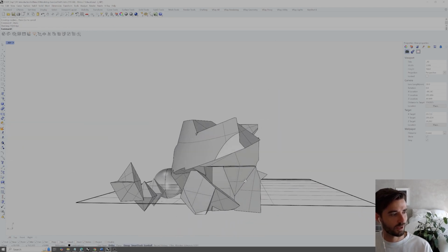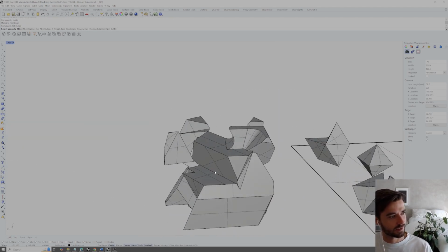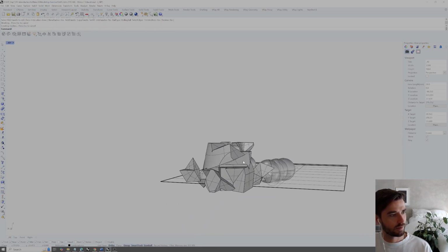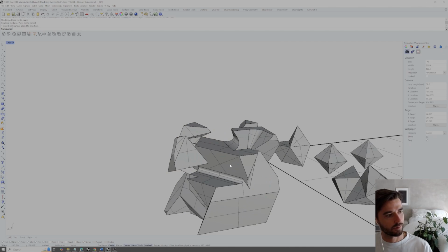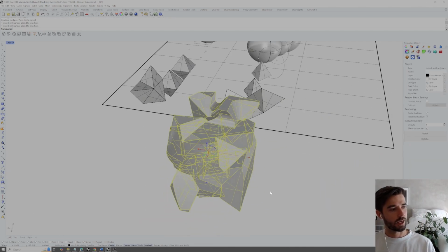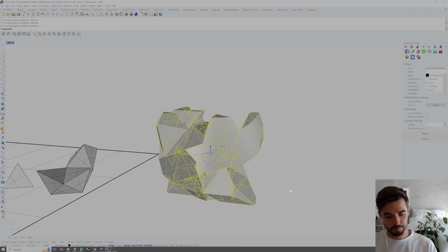It's not wanting to. Okay, then I will go ahead and skip that. Okay, there you go. It's still a closed solid poly surface. Okay, so now what I'm going to go ahead and do is select that geometry, and I'm going to type Unroll Surface, enter, explode. We can just say explode yes, labels yes, keep properties yes.